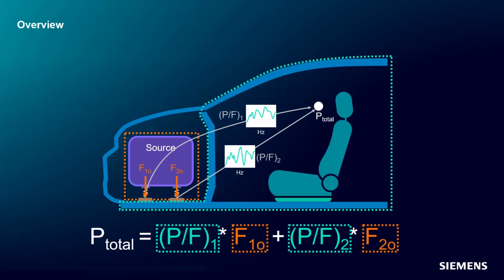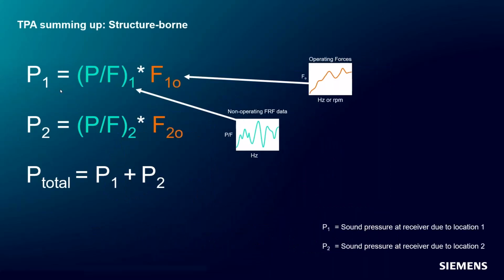Yeah, so from an experimental point of view, it would be very, very tricky to measure these directly. So it's not possible to measure these directly during operating conditions unless you really disturb the structure, and then your engine would probably fall out or something like that. And it's also helpful to have the FRF and the force, because this will tell us if it's the motor or the combustion engine that's really high, or if the structure is very sensitive, so we'd have even more insight. First, we'd know which path is the biggest, and then we might look at these things to figure out what to do. Like, do we need to address a resonance or something else?